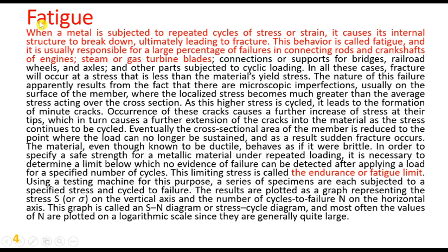Then fatigue. When a material is subjected to a repeated cycle of stress or strain, it causes its internal structure to break down, ultimately leading to fracture. This behavior is called fatigue, and it is usually responsible for a large percentage of failures in connecting rods, crankshafts of engines, gas turbine blades, connections or supports for bridges, railroad wheels and axles, and other parts subject to cyclic loading.